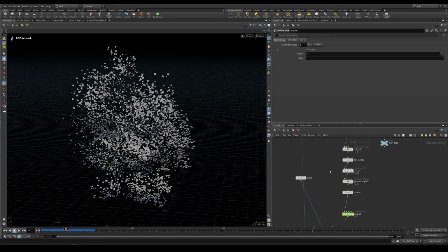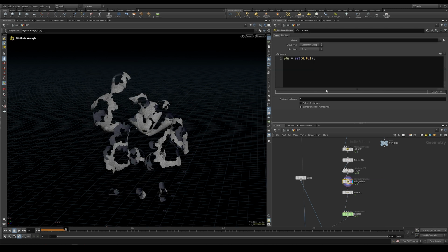This is because Houdini, in order to make the angular velocity work, needs the orient attribute, which is a quaternion. The normal and up vector wouldn't be enough, so we need to compute this orient. Let's rename this wrangle to calc orient. And in here, the first thing we want to do is to retrieve the velocity vector, or rather the normal, and the axis vector we calculated here. So let's delete this line.